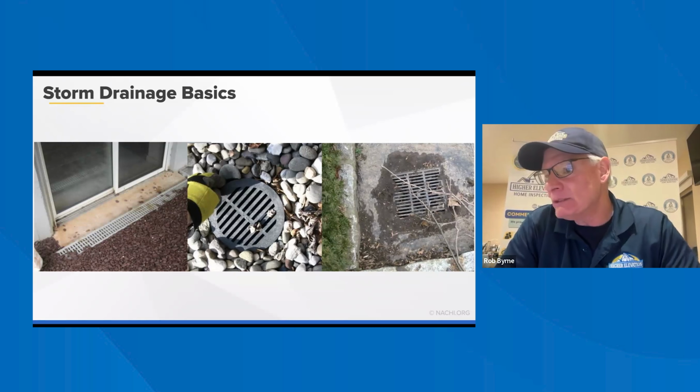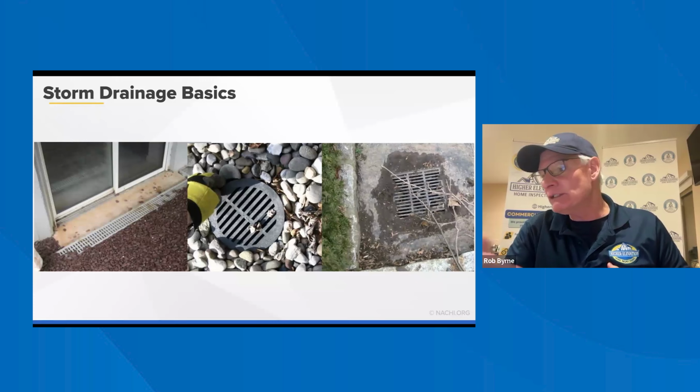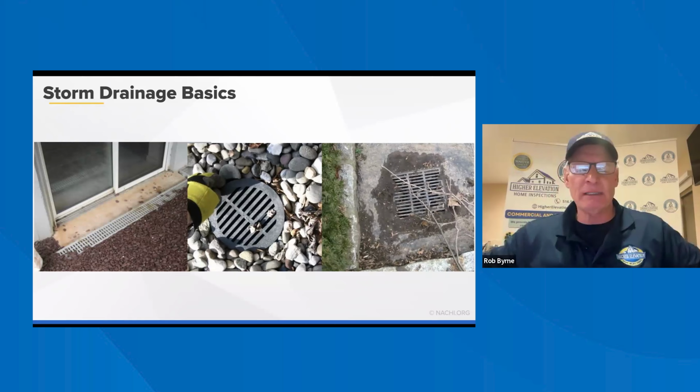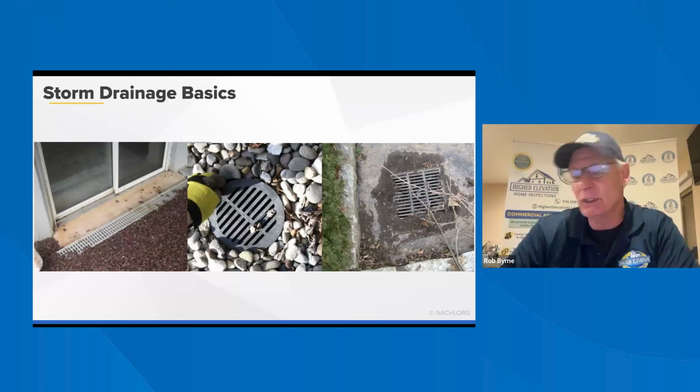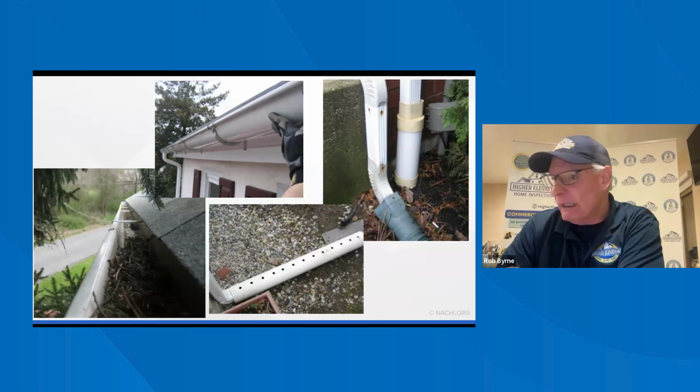And that's pretty much it, the rainwater should drain to an acceptable point of disposal, such as retention basin, river, streams, ponds, public storm drains, or the land surrounding it. If you're on big property, a lot of times they just push the water away from the house, and as long as it's going downhill, they're doing a good job.